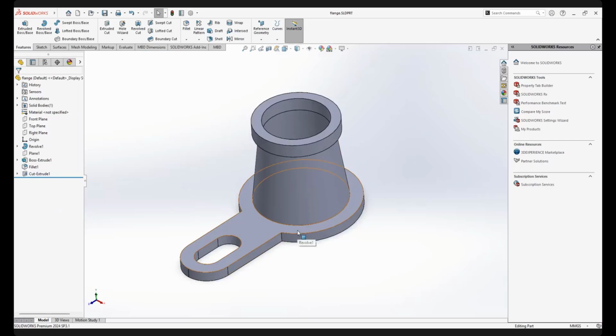We can do circular pattern. Watch me, guys. This is not mirror. It is circular pattern, because the number of arms together with the original one is 3. Circular pattern is not under sketch mode, it's under feature. Under feature we have the submenu. Not mirror. Can you see that is a linear pattern? If I click the arrow here, we have the second one. Linear pattern is more of a rectangular array shape, but this one is circular pattern.